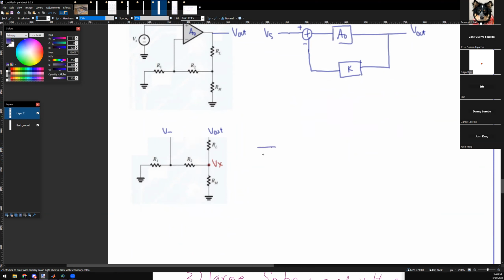So here you go. You want V out and you want to get to Vx? Easy. All you need to do is tell me the total resistance. Which is the top resistance? The top resistance connects between these two, and the remaining is the bottom resistance of the voltage divider. That's how you get to Vx. Agreed? Okay, so the bottom is going to be the total resistance RL plus RM in parallel with R2 plus R1.